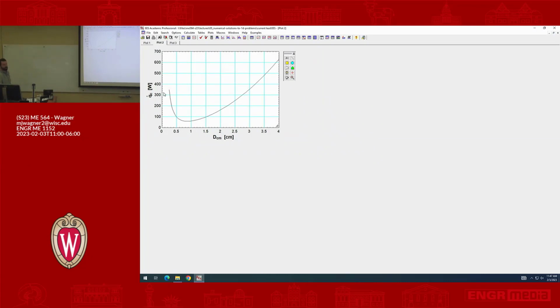So you're basically heating this wire way up. Okay? There's a minimum. And then as I make the diameter larger, it goes back up again, which means now this conduction along the axial direction from ambient temperature into my cryogenic region is becoming dominant. So you can use these to actually do a lot of this optimization for you.